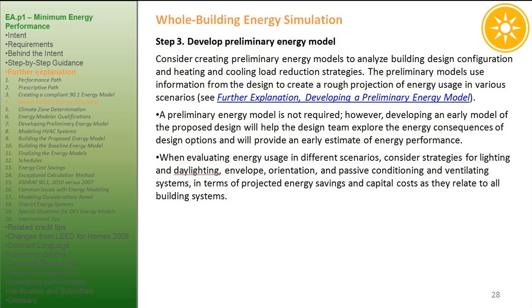A preliminary energy model is not required, however, developing an early model of the proposed design will help the design team explore the energy consequences of design options and will provide an early estimate of energy performance. When evaluating energy usage in different scenarios, consider strategies for lighting and daylighting, envelope, orientation, and passive conditioning and ventilating systems, in terms of projected energy savings and capital costs as they relate to all building systems.